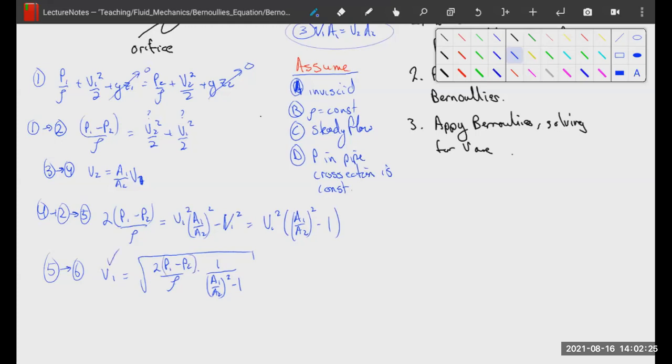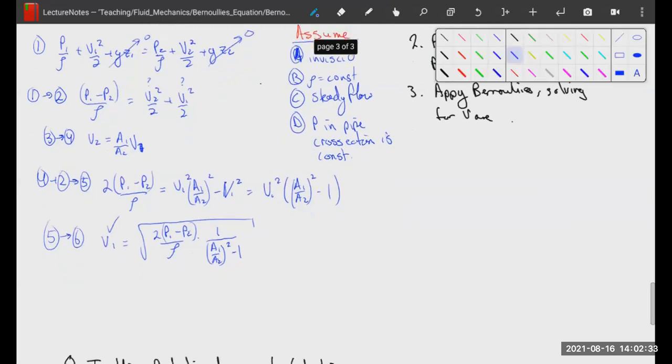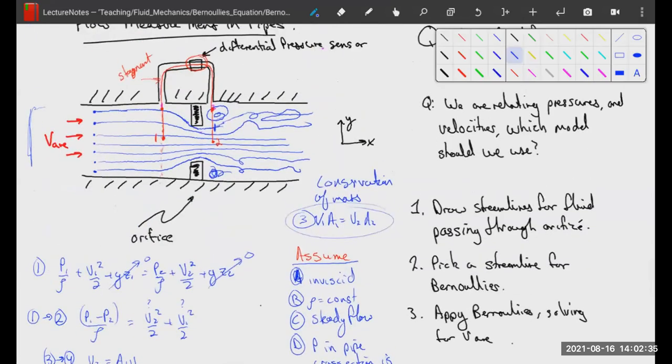And this is called an orifice pressure sensor. You can buy them. This is a cheaper version. What's important to know here is that this area is not actually as easy to solve for as you think it might, right? As the velocity in this fluid increases, the streamlines before the orifice stay roughly the same. They overshoot these corners more and more the higher the velocity gets, or the higher the Reynolds number gets. So at very high Reynolds numbers, you can get large overshoots.